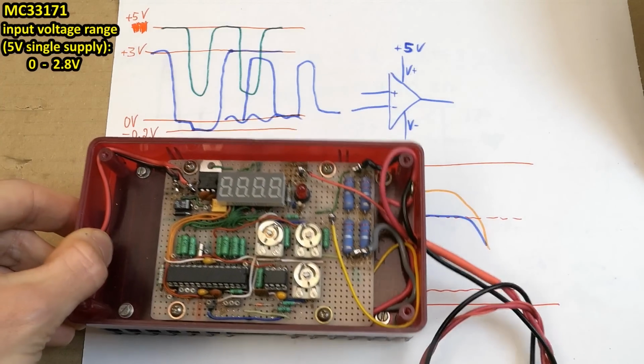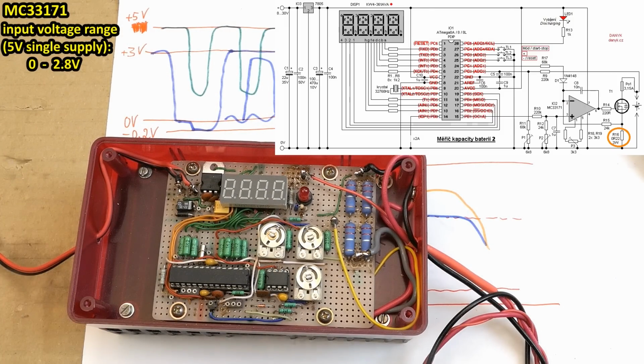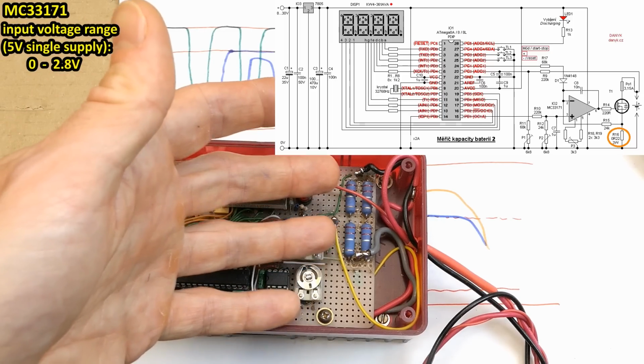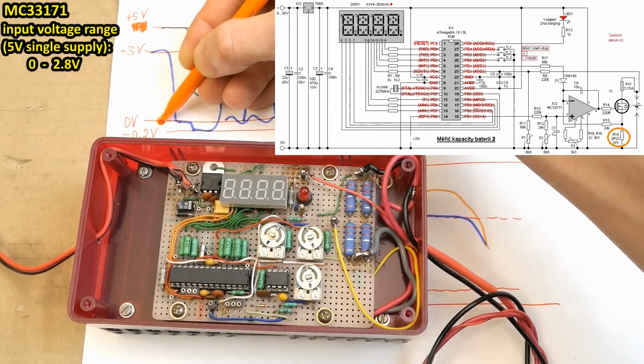For example, my battery analyzer is using an op-amp running at 5 volts non-symmetrical, and it's sensing the voltage on the current sensing shunt in the negative rail, which is basically the 0 volt rail because it's not symmetrical, and the op-amp has to be able to operate with 0 volts at the input.